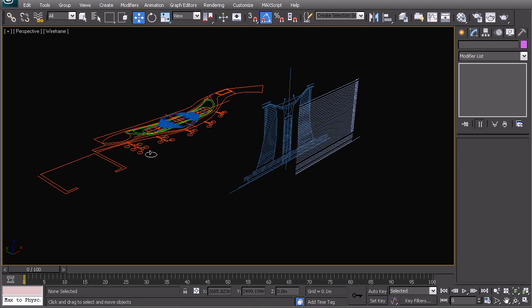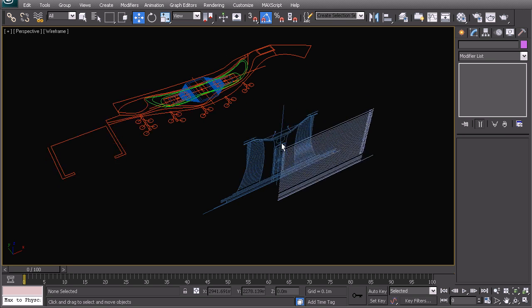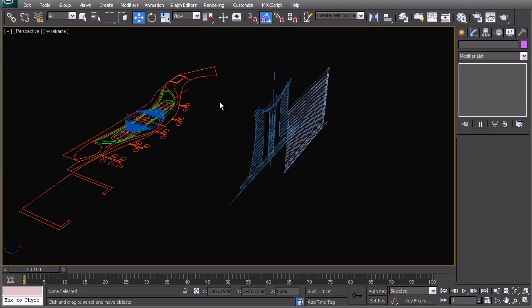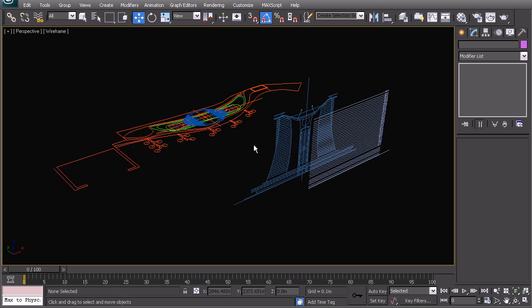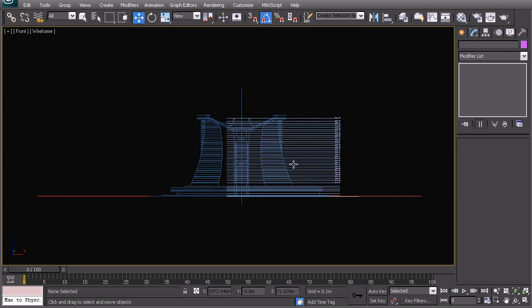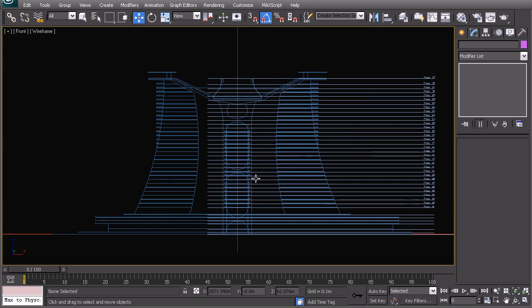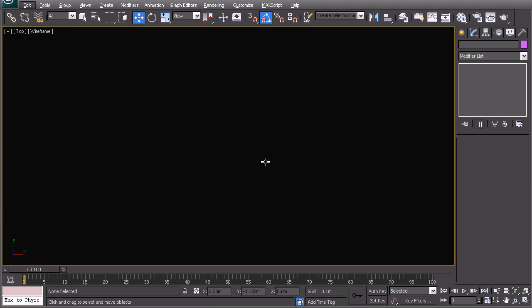What we've covered, just to recap, is we've imported our CAD plans and we've checked the position in the X and Y according to our existing model, and then we have rotated up the elevation and then the grid lines to be correct in the right viewing plane, so that we can easily go into your front view and you can model in both front view and plan view.